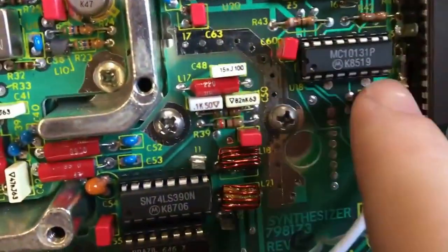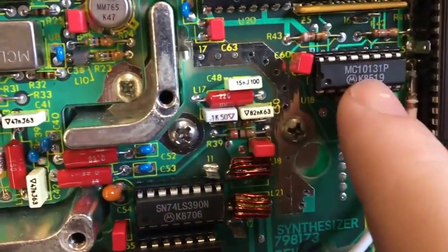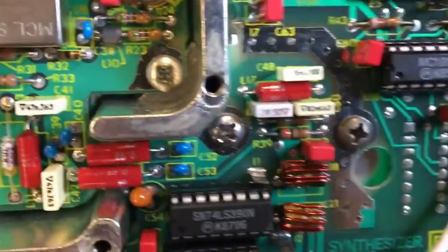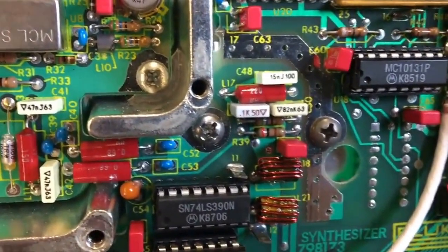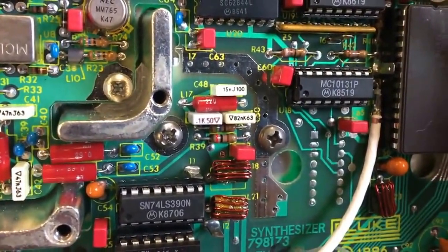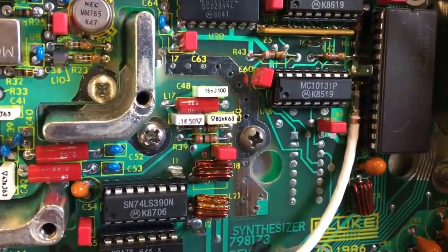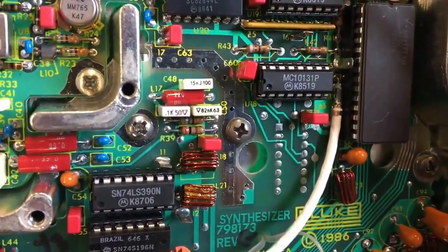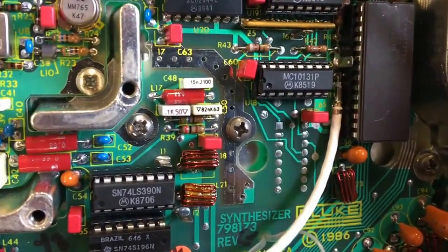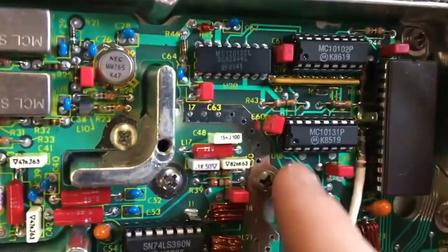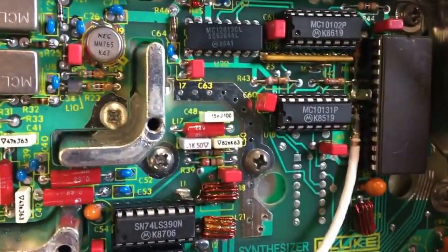Right. So that's the culprit right there. This one I see here was responsible for 3 faults. The bottom end not working below, I think it was below 20 megahertz, it played up, and the very bottom, I think it's about 10 kilohertz to 40 kilohertz not working, and the 20 megahertz / 10 megahertz offset on certain channels. So that's the fault to watch out for. If you get that, then this chip is something worth looking at.